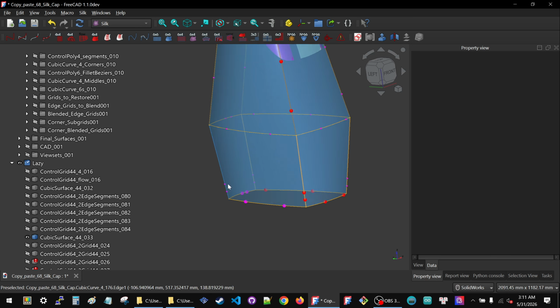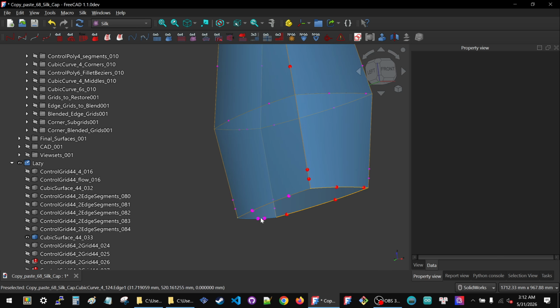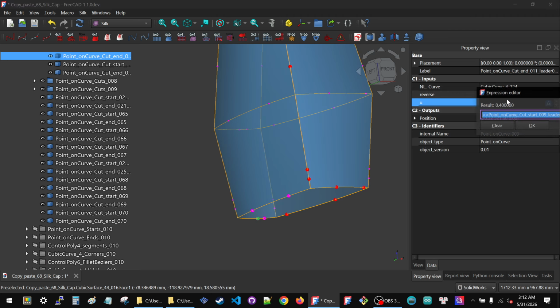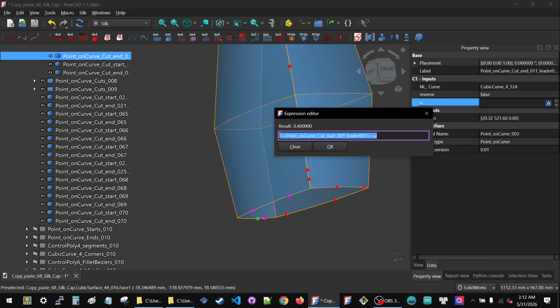Here is the formula that actually works. I'm going to find that point. It's this guy right here, and I know because it's driven and it's 0.4. I'm going to type equal. I get its formula. The way I get it running in the right direction is I type 1 minus. This is how I reverse the reference of the end and the beginning here. I don't want to adjust everything else. I just want this point here to correctly match this one, and I don't want to edit all the other formulas, so I type 1 minus.